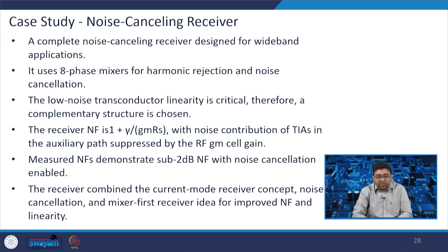So, a complete noise cancelling receiver designed for a wideband application. Here it uses 8 phase mixers for harmonic rejection and noise cancellation. The low noise transconductance linearity is critical, therefore a complementary structure is chosen. So, the complementary structure will help us to improve the linearity.